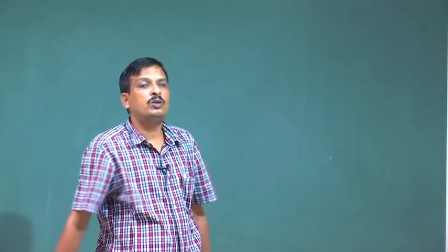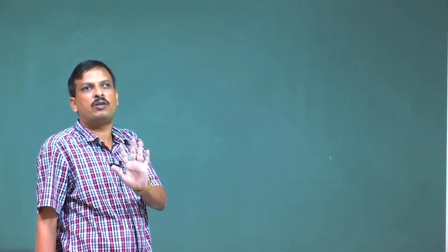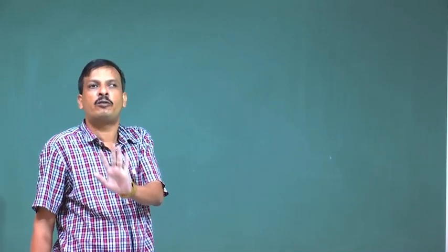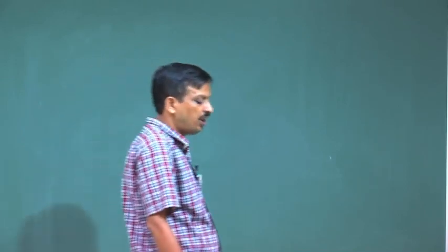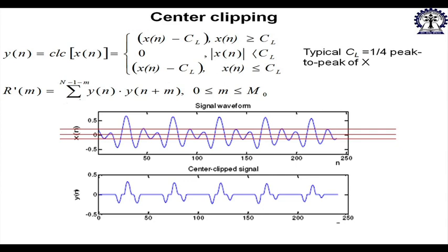Okay. So, we have said the cross correlation is one of the methods to enhance the result of the autocorrelation technique. The other method is called central clipping. If I have a speech signal like this, I want only the central part, because if you see the F0, filtering also, clipping, and F0 up to 500 Hz is sufficient.